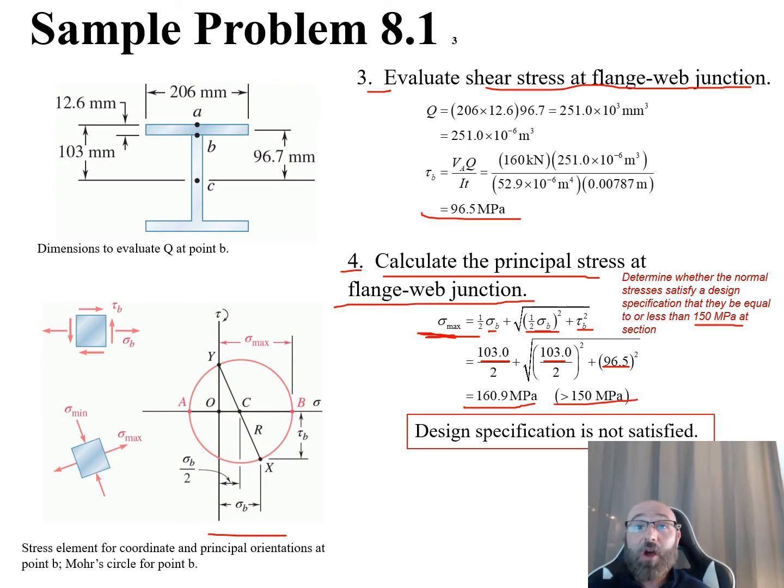This is greater than our 150 megapascals. So therefore, the answer to our question, the problem statement, does this satisfy the design specifications? No, the design specification is not satisfied because it's not less than or equal to 150. It is greater than 150 megapascals.